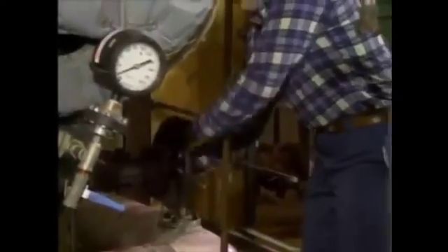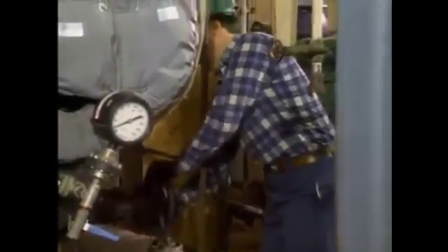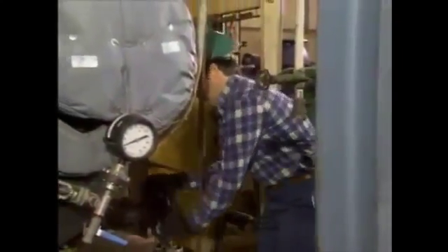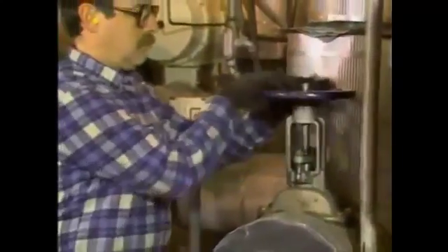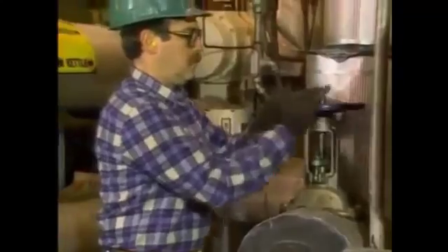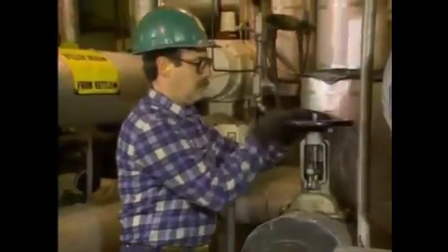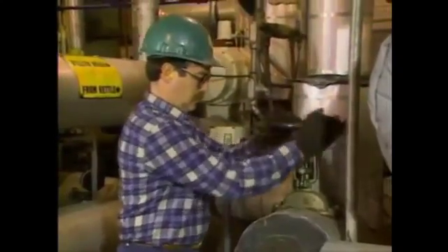There are many ways that air or other gases can get trapped inside a heat exchanger. For example, this can happen during the startup of the unit. During startup, the heat exchanger should be vented to remove unwanted gases. If the venting is not complete, gases will remain inside the unit.